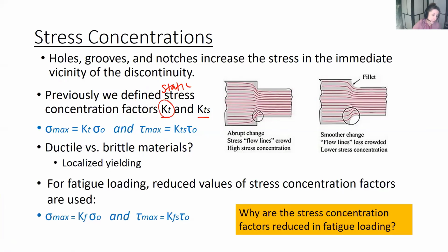KT was for bending or axial loading. This little 0, this is nominal. That's what that means. And then, for example, your maximum shear stress is the product of the stress concentration factor times the nominal stress, which for us in that class is usually Tc over J.